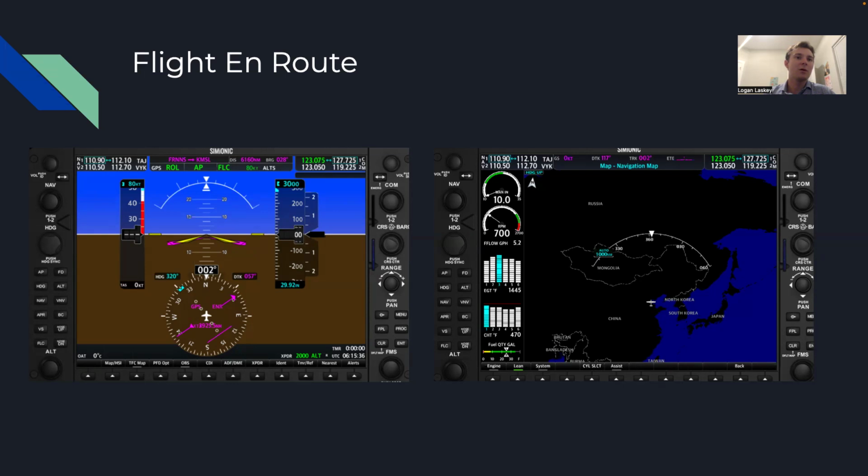And all while this is happening, I'm monitoring my airspeed, my altitude, and my engine instruments as well. Something else I would do once I'm establishing cruise is hit Engine, Lean, and then adjust the mixture until I'm lean perfectly, with the bars being the biggest they can be. That's how I know I'll be in the good sweet zone in the lean, and have my engine performing as proficiently as possible.